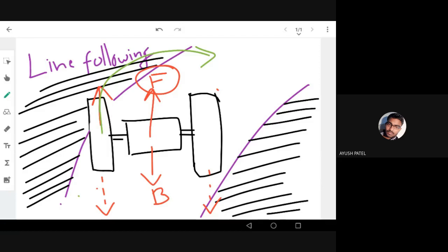So this is one option. Another option is to improve the speed of turning, or the turn radius. If you want to turn right, you should stop the right wheel, or to improve the turning, you have to rotate the right wheel in the opposite direction. That is also better. For example, here the left wheel goes in the clockwise direction and the right wheel goes in the anti-clockwise direction. So the vehicle, a robot, is going to rotate in which direction?